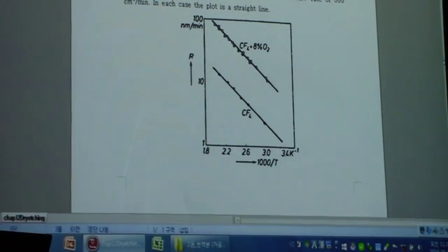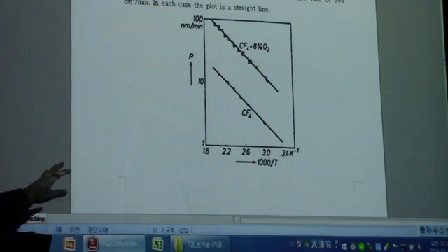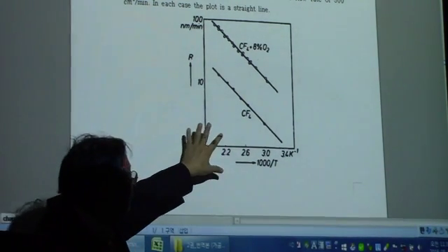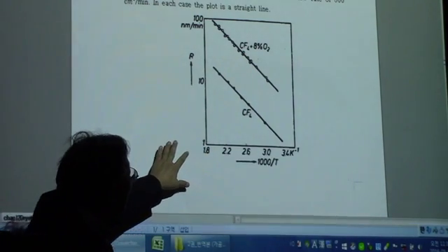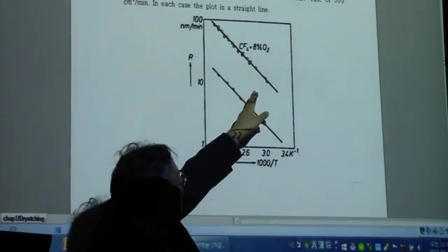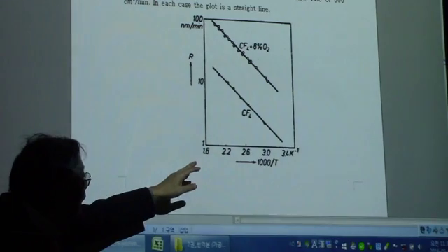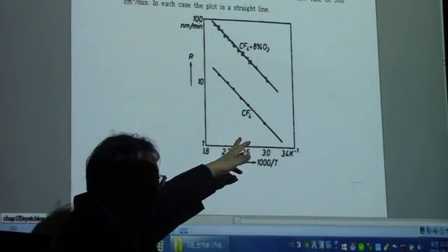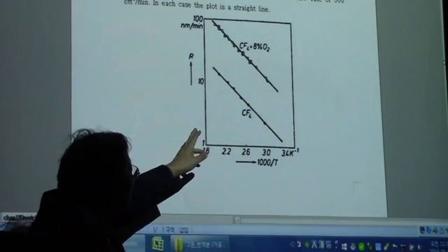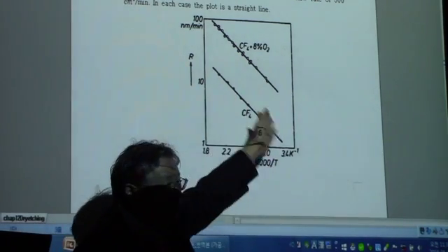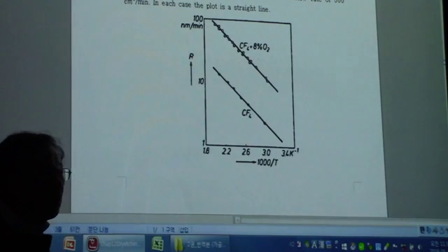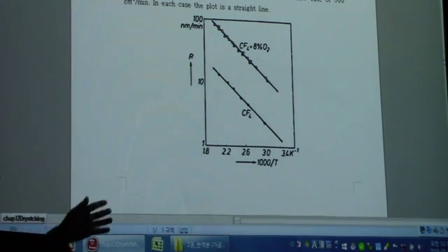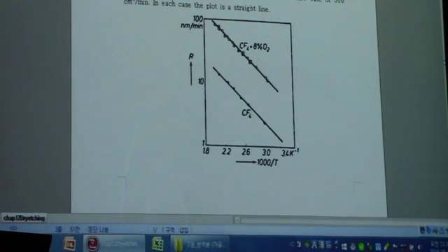And this particular example is a silicon nitride etch. The 8% of oxygen is used, compared with the no oxygen case. And one thing you can notice here is that the straight lines both have the same slope, even though the etch rate is different, but the slope is the same.